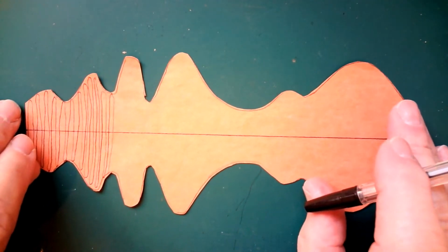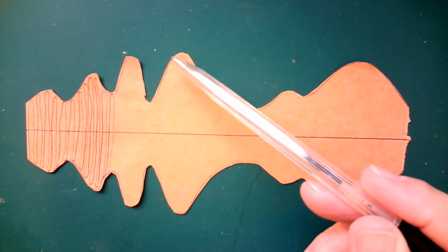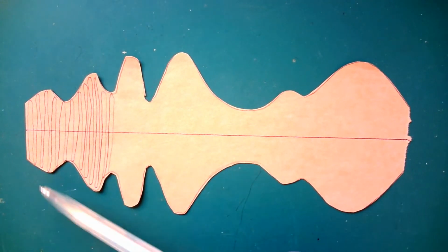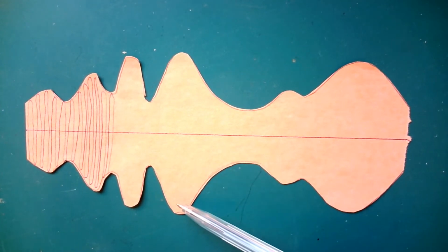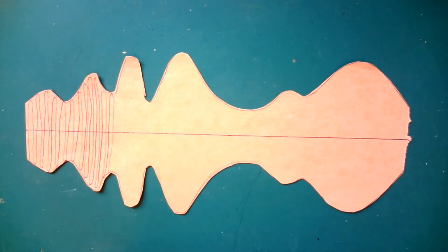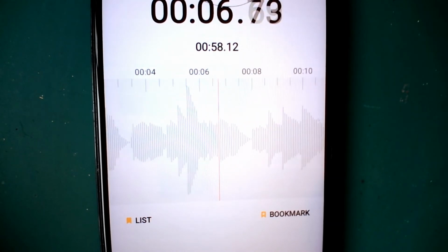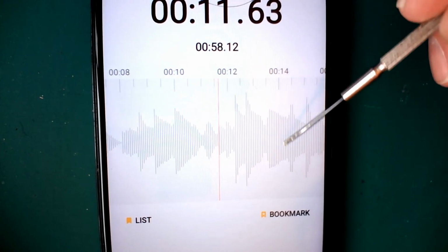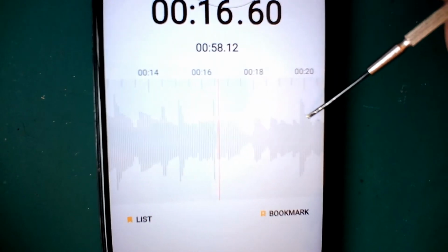Now it turns out that when you put it into a modulator, you don't just modulate the top of the radio wave, you also, by the function of the modulator, modulate the lower part of the radio wave as well. And this lower part is an exact image of the top part. This radio wave is being amplitude modulated. You can kind of see the radio wave, but the tops and bottoms of the radio wave are going up and down in exact sympathy with the sound of my voice.